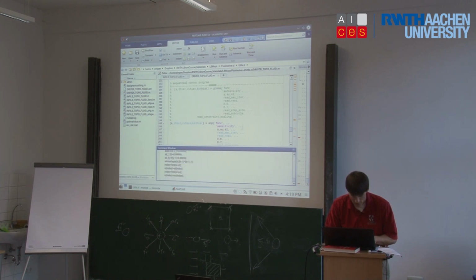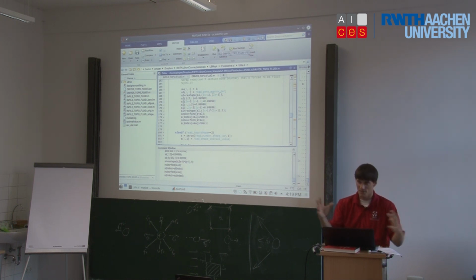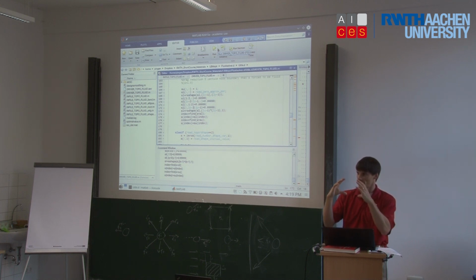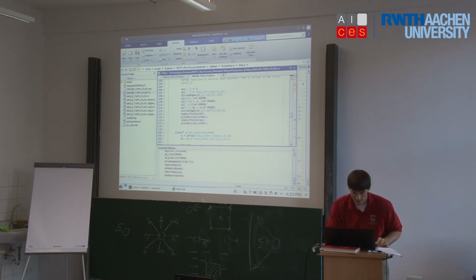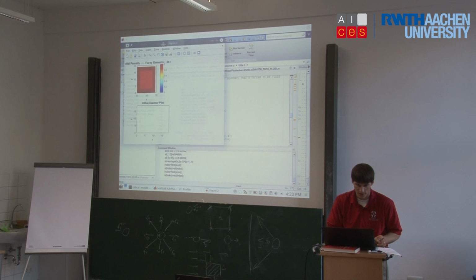Let's kill this for a second. Let's decrease the size of the boundary block a little bit. 3, 3, 3, 3. When I scaled the domain smaller, I didn't make my boundary box smaller, so my 10% was basically the whole middle had to be solid. So run it again. Okay, now we have a bigger box where our design can be.